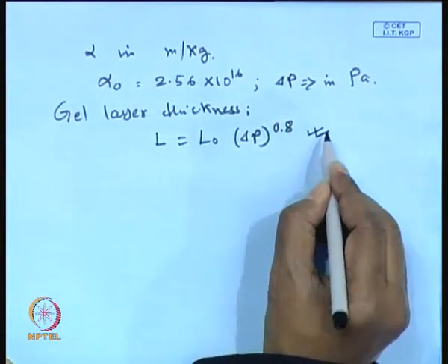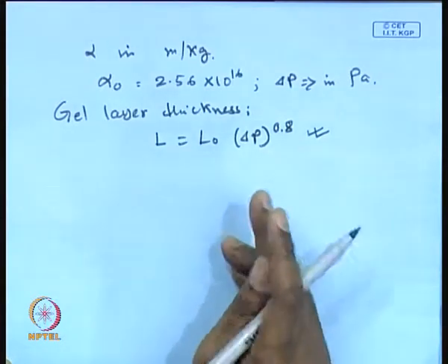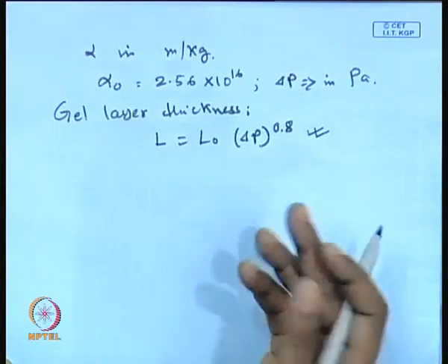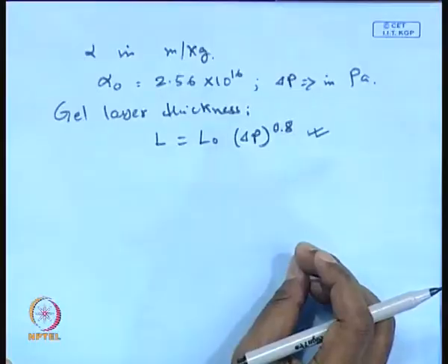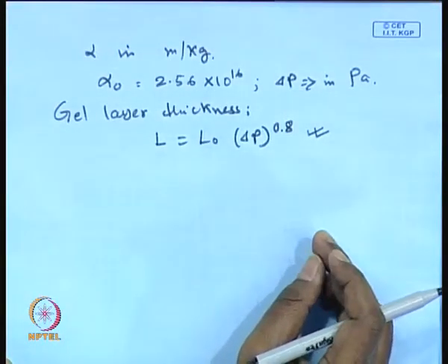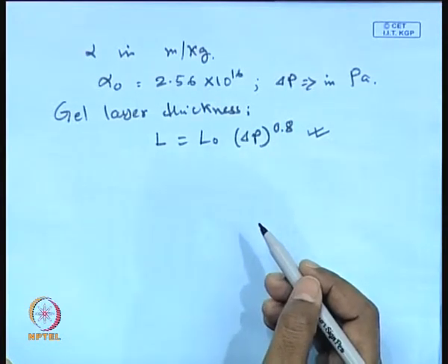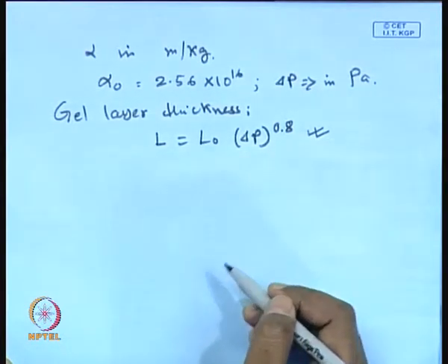How do you obtain this? You can obtain this by microscopic observation. That means, after the experiment, dry out whatever is depositing over the membrane surface, put it under a microscope and measure the thickness. Then do a back calculation and check how much volume was there previously, because in the solution it was in a gel state. So one can back calculate and find out the actual thickness of the gel layer under the solution, under the wet condition.